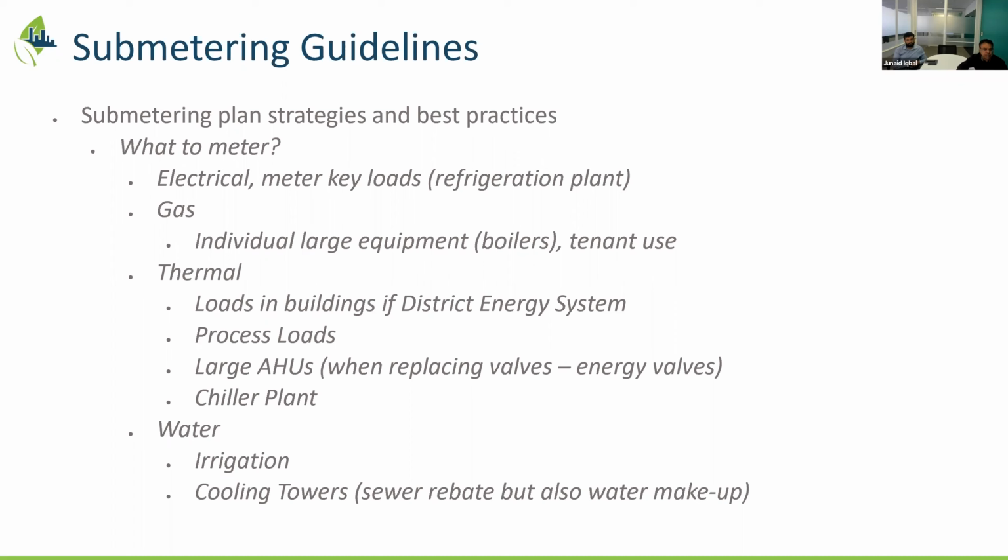And also, I don't want to forget this, because with the submetering information, we always have the ability to measure and verify energy saving for implemented energy conservation measures. Yeah, thanks for that. That last one's a really important one. I mean, they all are important, but one of the great things about the submetering aspect, especially in a big facility like a Terry Miller and in other buildings where there's big loads, is that you can really isolate it, and it's very easy to prove how effective a measure is, and also not only how effective it is, but how it can continue to be sustained in that way, right?